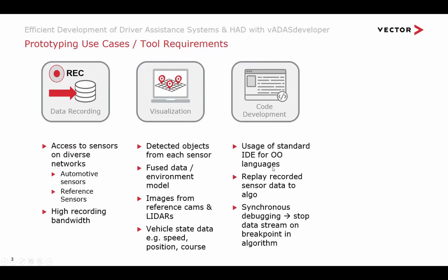Second thing is then you want to use the recorded data from the recording stage to replay that sensor data to your algorithm under development to stimulate your algorithm. And for that, it's very important that you also have a feature of synchronous debugging, so you can stimulate your algorithm with some data, and as soon as you hit a breakpoint in your algorithm, the data stream at that point would also stop, so you can step through your algorithm without keeping the link to the external, let's say, stimuli, and also be able to have a meaningful way through your algorithm.